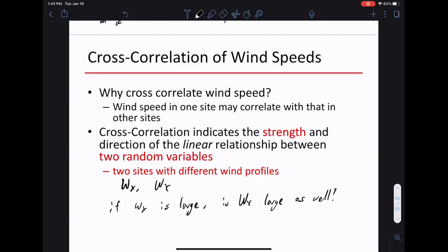Whereas if we have a lot of solar, we're probably not going to have quite a lot of wind. This is particularly if we consider the night and day behavior. Solar and wind are really anti-correlated if you take time into account. When you have bright, sunny afternoons, there is relatively little wind, and at nighttime, when it's very windy, you have no solar. So solar and wind are anti-correlated, and you often hear people say they're complementary to each other, which is just a less technical way of saying the cross correlation is negative.